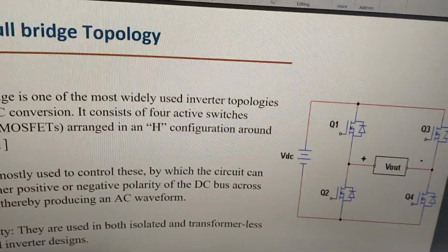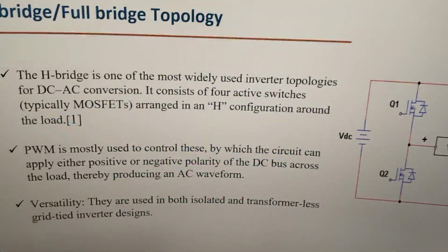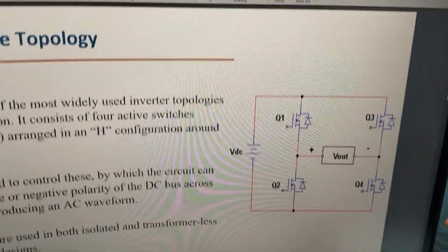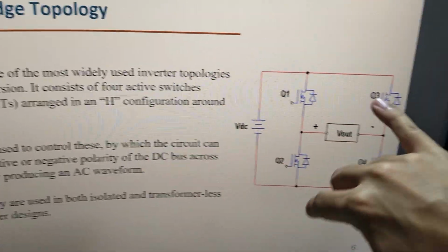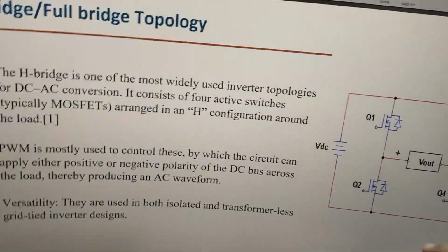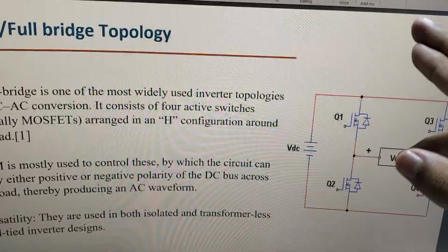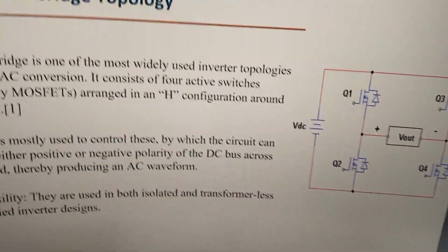And even within SPWM, there are two types. You have bipolar SPWM, which I just described to you, where you alternately turn the diagonal switches on. With this you can generate a sine wave which goes between plus VDC and minus VDC, so directly from this top to this bottom. And that's good and all.